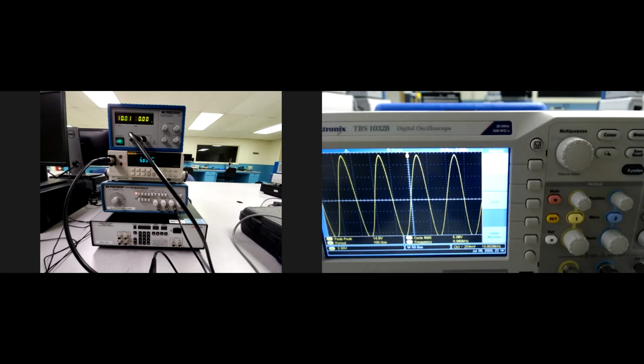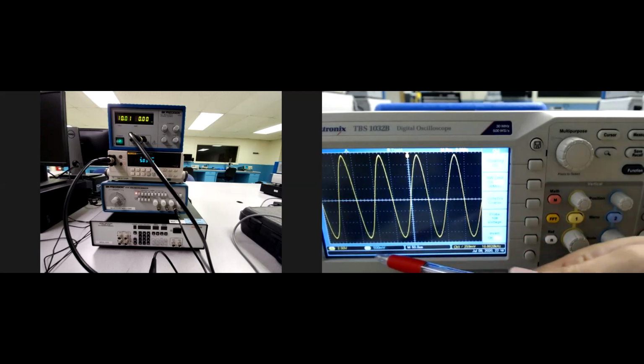Yeah, I can do it. Thank you, Henry. Go ahead, please. Turn on channel 2 by pressing the blue button 2. If this is off, this will allow channels 1 and 2 to be viewed simultaneously. Okay, so I'm gonna press number 2 right now. So if you take a look at the oscilloscope, you'll see my finger on top of the blue button. And as soon as I did, you were able to see at the bottom this blue legend that indicates that channel number 2 is on.